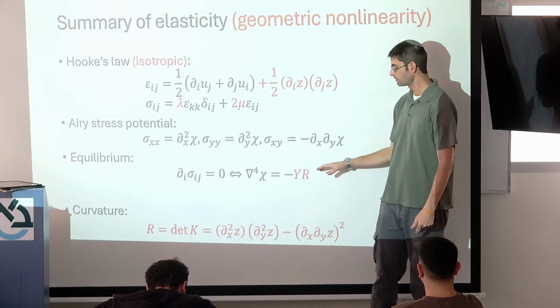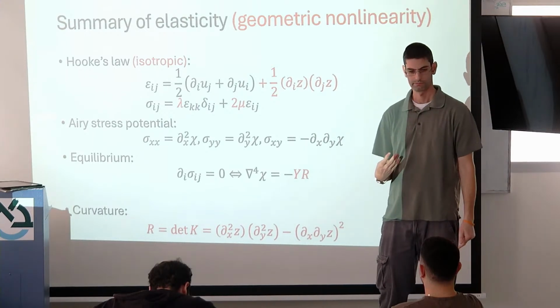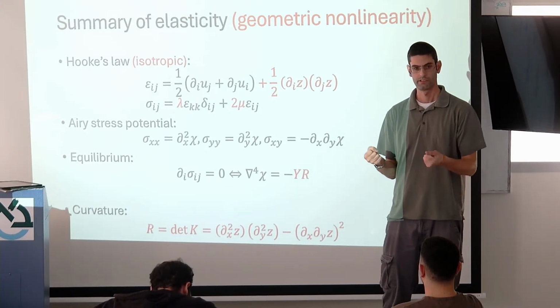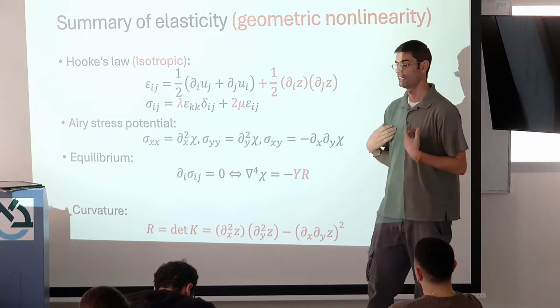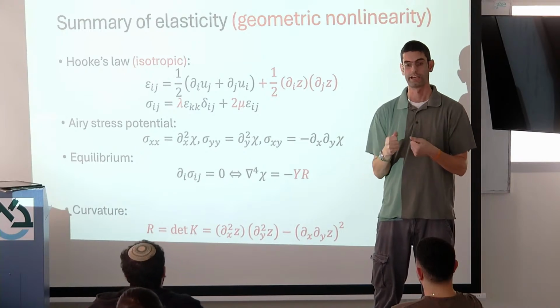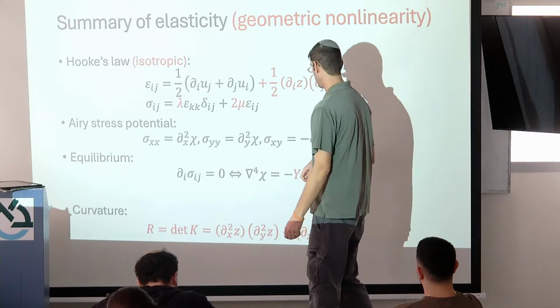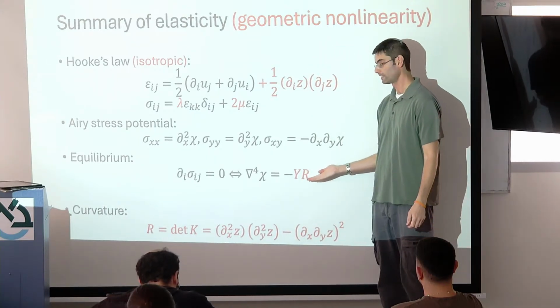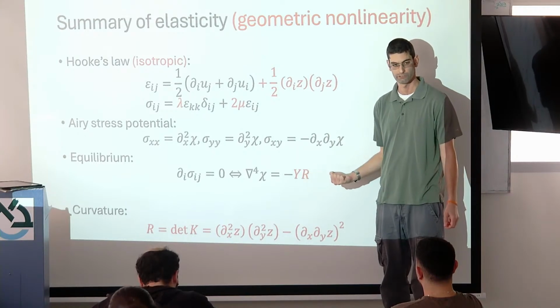Okay? So what that tells you is you cannot have curvature without stresses. I cannot take a system and curve it without creating stresses in my system. Because I might not be able to see it, but curving my material pushes the atoms away from where they would like to be. And what this tells us, for example, is that one of the ways that a material will respond is by trying to relieve these stresses.